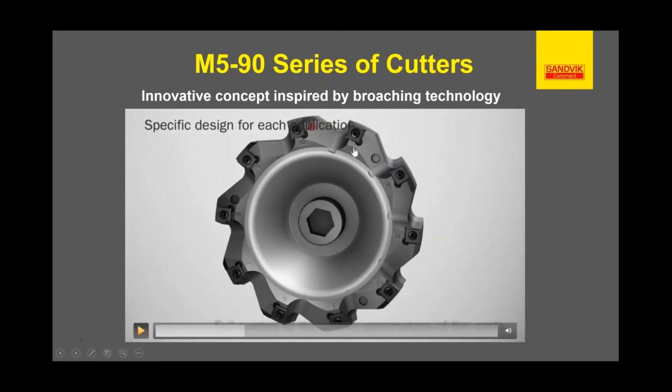I'm going to let this turn here, and then I'll stop it again. Okay, so you have numbers 1 through 10. This particular cutter has 10 inserts, which most of them do in this design. Here we talked about taking 1 millimeter depth of cut.